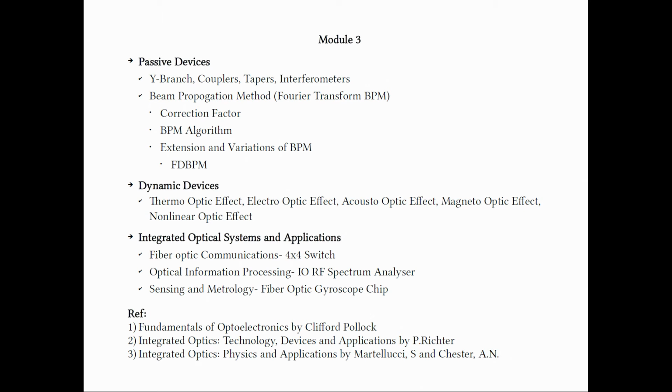optical signal processing. We can have signals, some of them could be attached to the electrodes, the IDT electrodes, and some of the signals could be associated as modulating signals to the light wave, and we can find out many properties of interaction of the light waves and acoustic waves or the RF frequencies using the acousto-optic effect. The magneto-optic effect effectively implies you apply magnetic fields to change the refractive index and other polarization properties of the medium, and we can make important devices like polarizers, analyzers and so on.